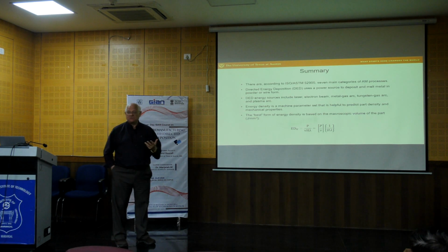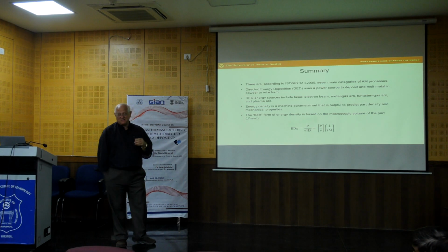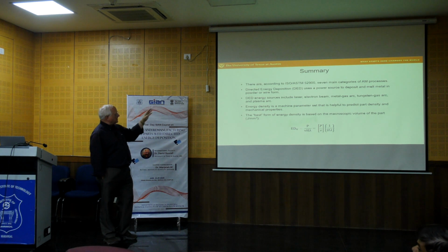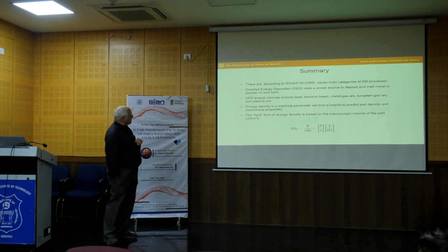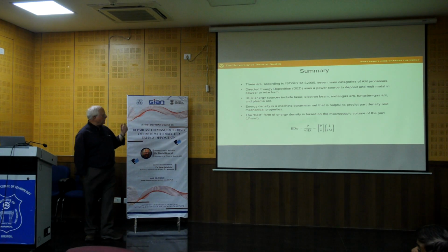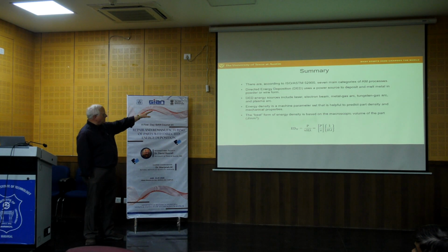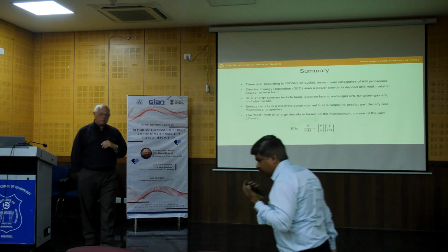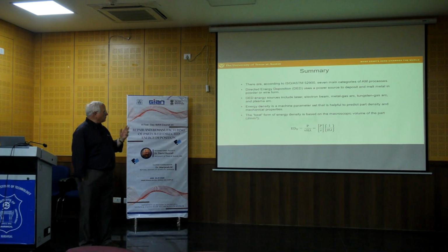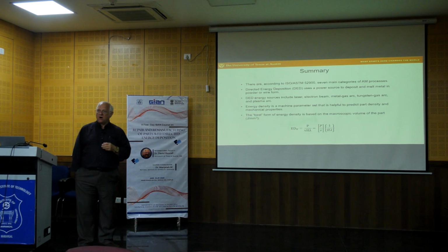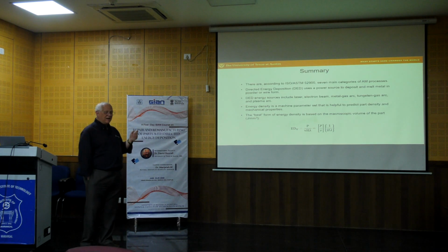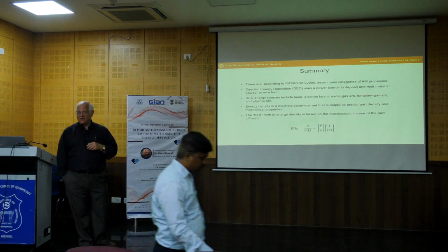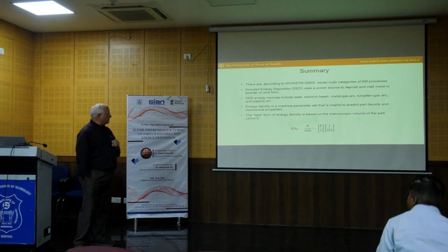But anyway, the committee is very active. We continue to look at technologies and evaluate them. So anyway, directed energy deposition. Again, we have a power source to deposit and melt the metal in powder or wire form. We talked about some of the advantages and disadvantages. We talked about the energy sources and that the energy density really is a key parameter to help predict part density and mechanical properties. We talked about that. And again, the energy density approach was really developed for DED. That was what his emphasis was.